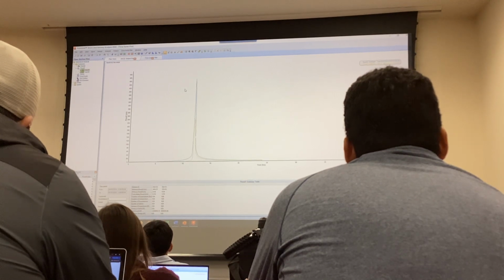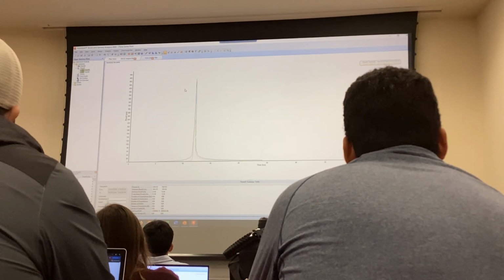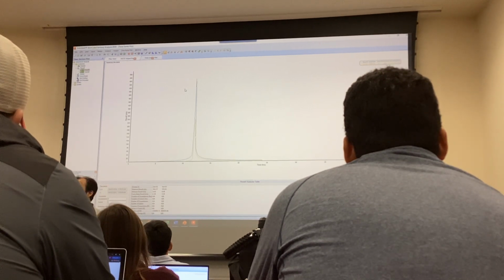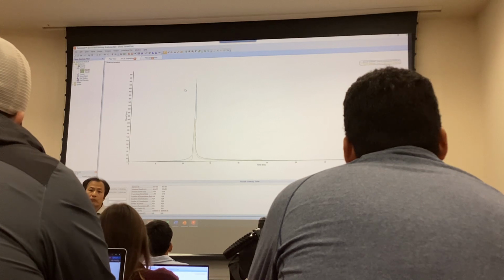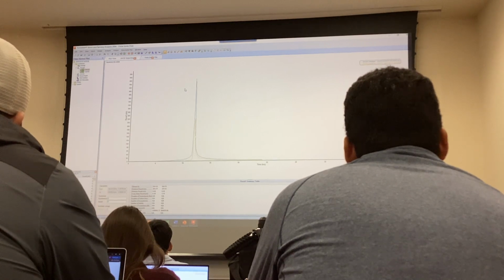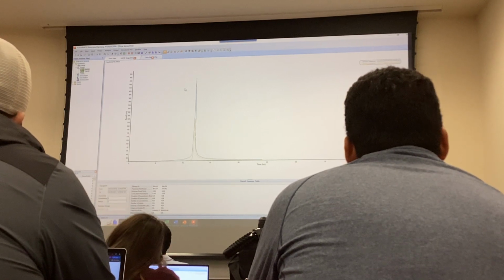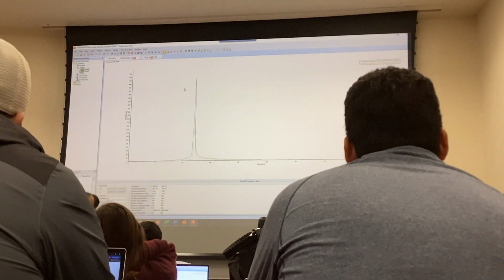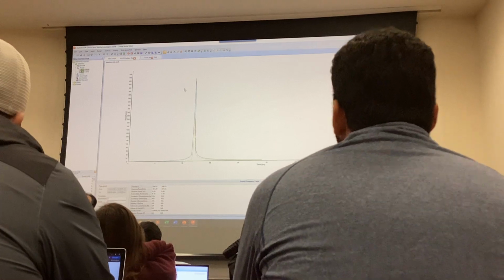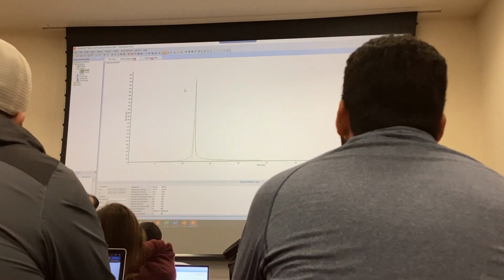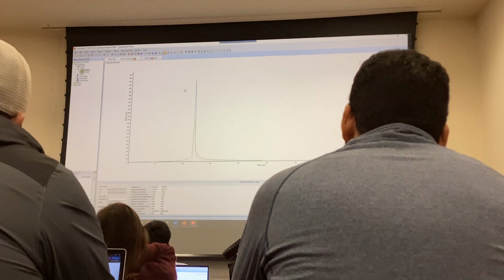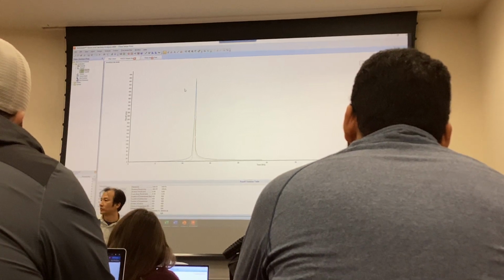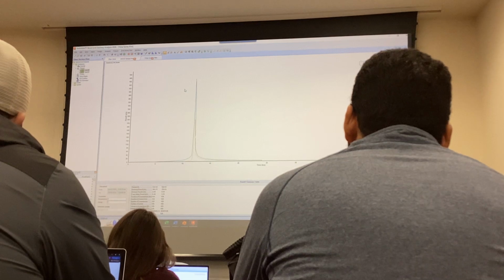So now the next question you're supposed to ask me is, great, you have a pretty graph. What do you do with it, right? So the next thing is we need to figure out how we can extract the volume based on the hydrograph you have. Because now you have the pre-development, you have the post-development hydrograph, right? So you can now technically copy these coordinates of this hydrograph out and do the analysis just like what we did in class to end up with a volume of your detention.